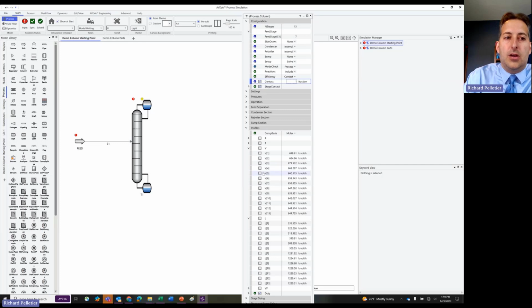Well, in here, you are the initial estimate generator, right? While this is in configure mode, you are the one that's doing the initial estimate generation. And then when you switch this to solve and contact equals 1, you're supplying the algorithm, in this case, the APS solver, with the initial estimate values in order to try to solve the more rigorous calculations. Right? So this is how it works in APS, and this works, like I said, about 95% of the time.